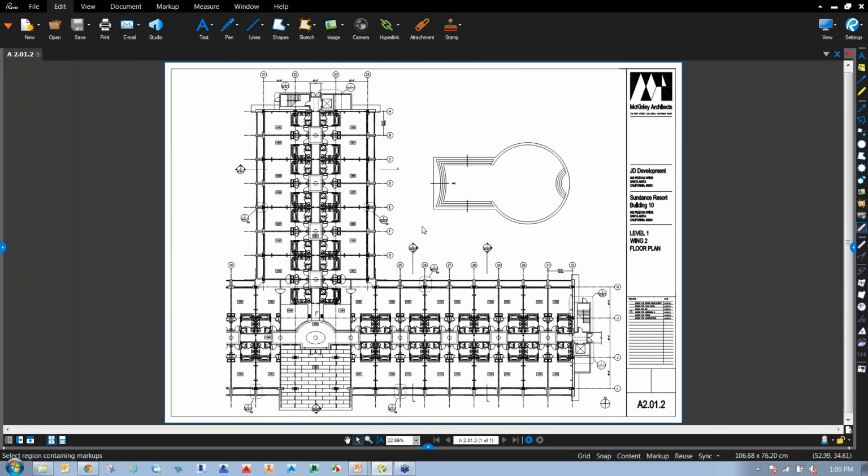All right, so now let's get into the actual markup side of it. As I said, we have got the markup tools available on the top here. We also have got this toolbar on the right that I can use to create markups. This toolbar on the right of my screen, or this panel bar or ribbon tab at the top. So if I, for example, expand the text flyout, we've got all these different text-related commands, or text box, callout, typewriter, note, and flag, and so on.